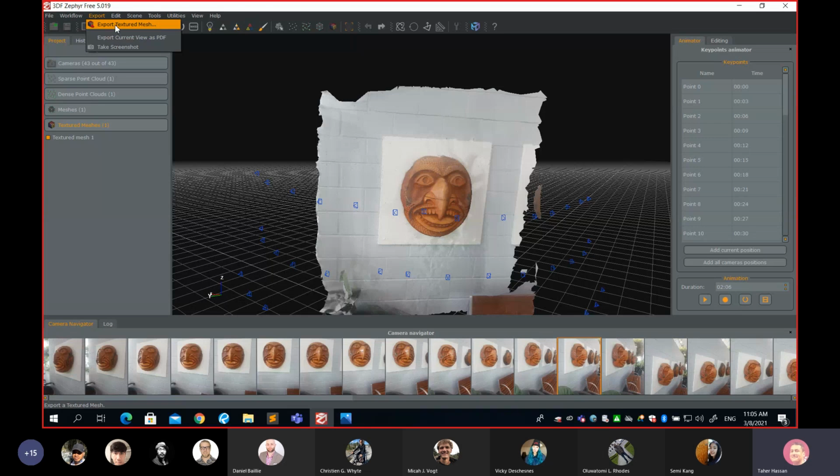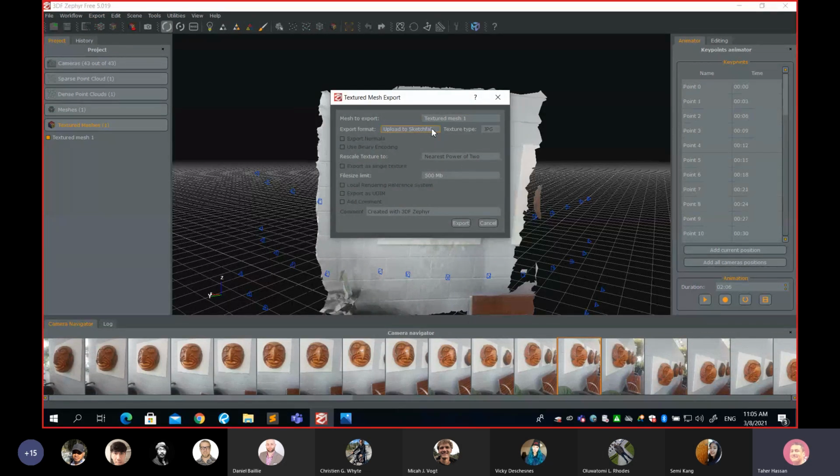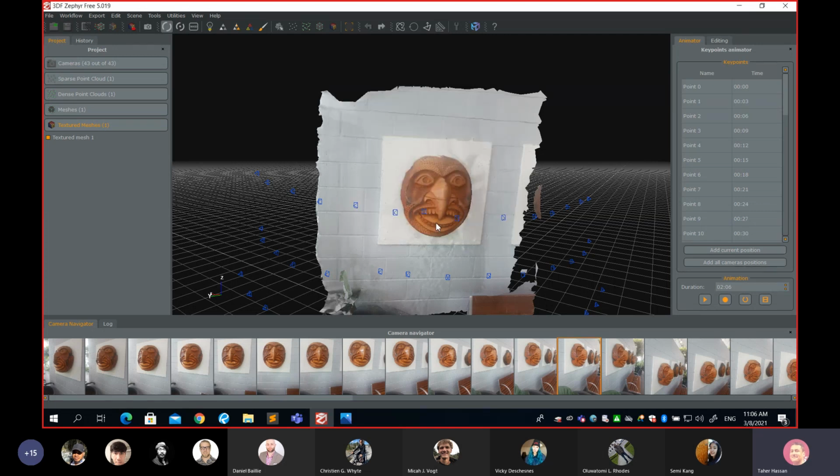However, the other option is you go to export, and there are some formats here: .ply, .obj, or .glb. In my tutorial, I mentioned OBJ and PLY because those are very popular formats in 3D printing. So I can turn my project into PLY or OBJ and print it on my 3D printer. That's very common right now: they do a scan with photos, turn it into a 3D model, export an OBJ or PLY file, slice it, and then print a 3D object.